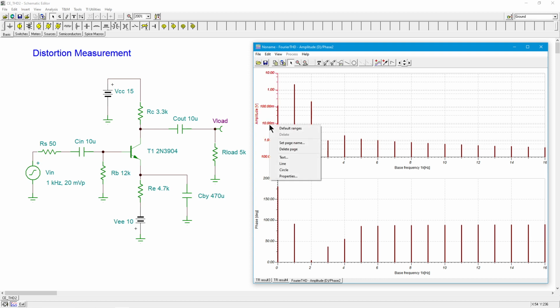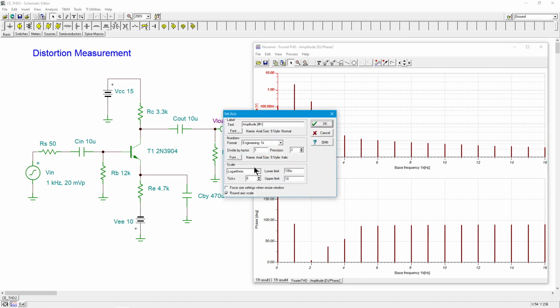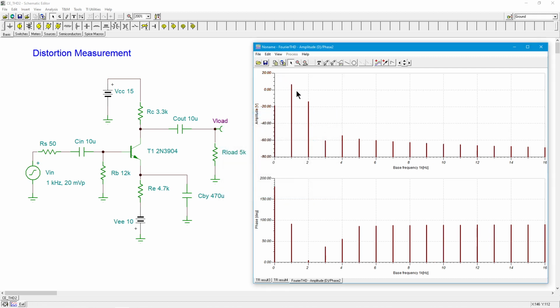You might also want to do this with a decibel layout that sometimes works a little nicer. So you can see it in terms of decibels, but it's the same basic shape when you do the log, because really dB are logarithmic, so there you go, right? And now you can see what's what. So here's the thing to remember, and that is you can have two amplifiers that have the same THD, right? Amplifier A, let's just say it's 2%. Amplifier B, also 2%.